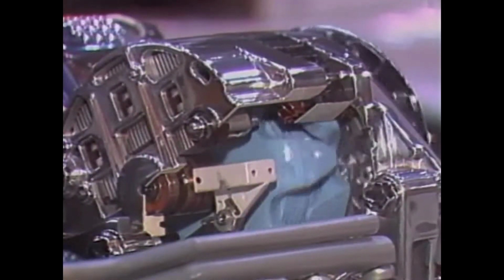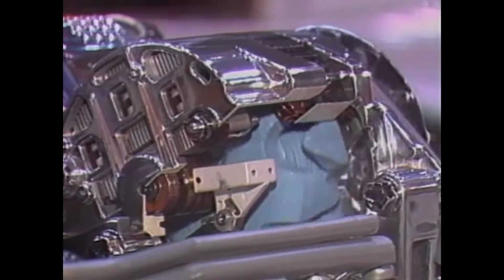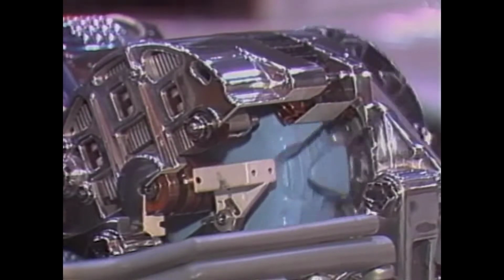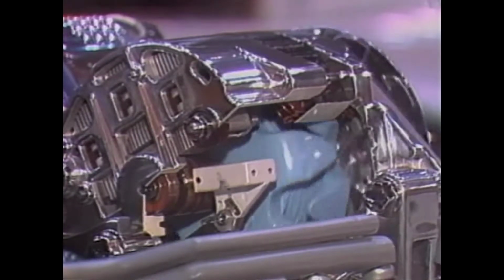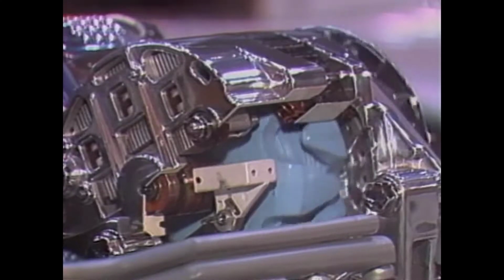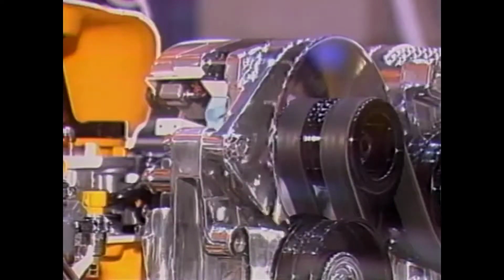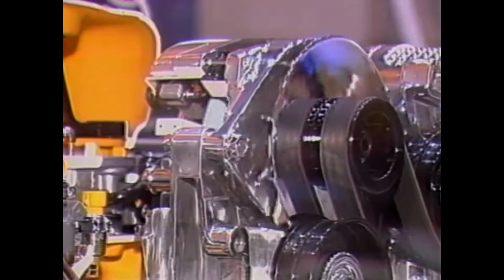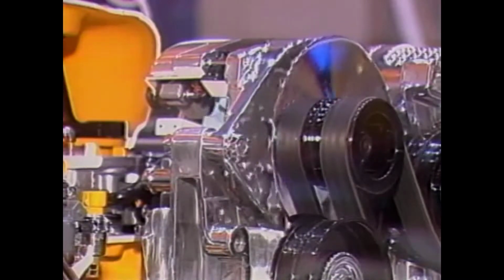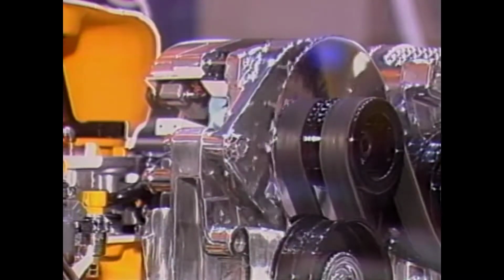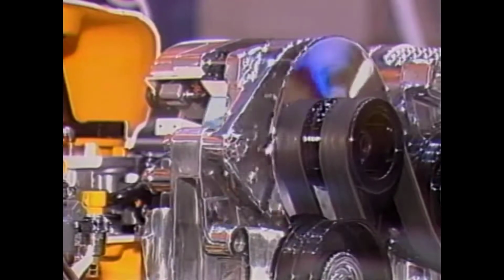This cutaway shows the rotor spinning inside the stator and front and rear housing. Also, note the brush holder mounted over the slip rings. This front view shows the drive pulley and fan. Picture how the fan would throw air outward, pulling air through the inside of the alternator to cool internal parts.